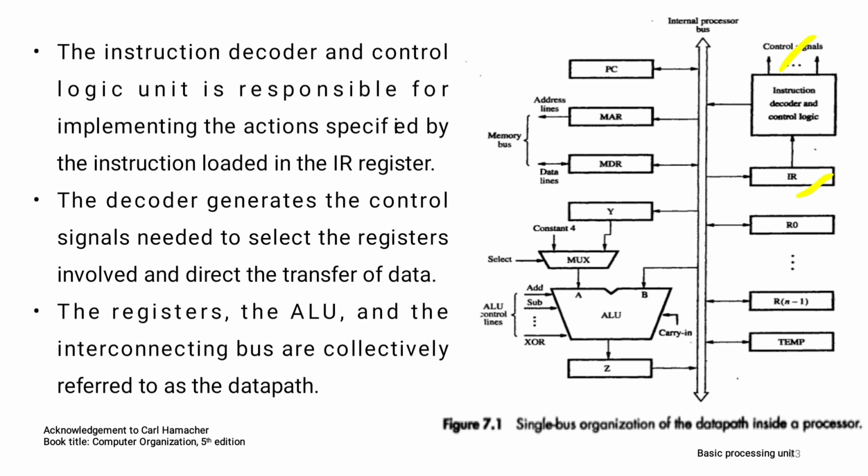That instruction will be decoded by the instruction decoder to know what operations must be done and where the operands are. To execute that operation on those operands, the control logic will generate corresponding control signals and activate the different parts of the processor along with the ALU to do that operation.